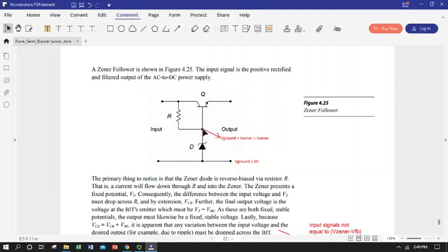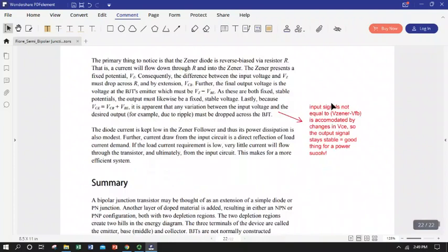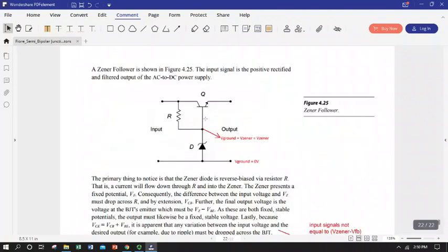So we can apply what's effectively a constant base voltage going in and basically have that relationship there and still have some current that we can flow into the base at a particular voltage. So the input signal is going to be pretty much equal to, it will open the transistor if it's equal to the Zener potential minus the forward bias voltage necessary to get across here, as this is already at a fairly high potential.